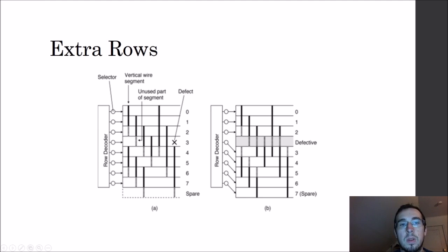For the next part of this video, we're going to talk about fault tolerance methods that can overcome the previously mentioned faults. One of these methods is pretty basic. It's called extra rows, and what it does is it adds multiple rows of PLBs and wire segments that are not necessarily the same thing, but they can take over in the event of a fault in a certain section.